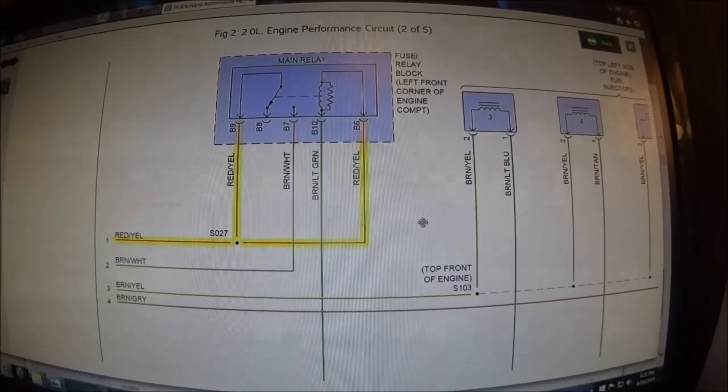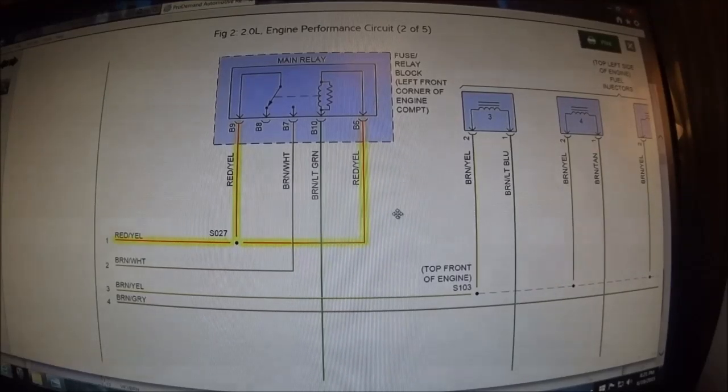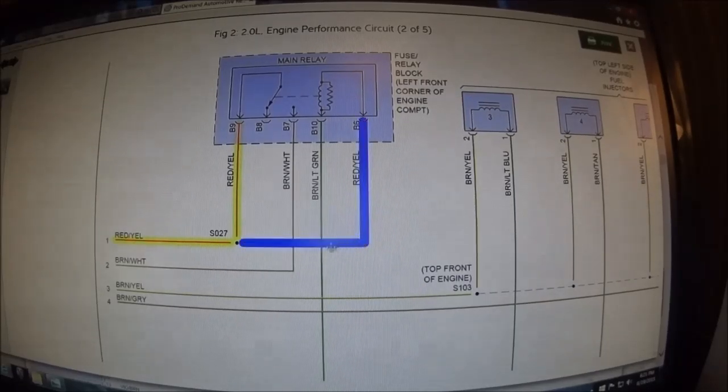So what I did was I opened the harness up in the truck, which I'm gonna put a picture in and show you guys, in a still photo that I have of the damage. The wire was once repaired, not by us, but it was repaired at some point or another. This vehicle was never to us before, so I had nothing to go on. I had no history or anything. When I found it up inside the wire loom, I could see the repair was done, and the wire rotted out and broke. So we had lost the power to the coil side of the relay.